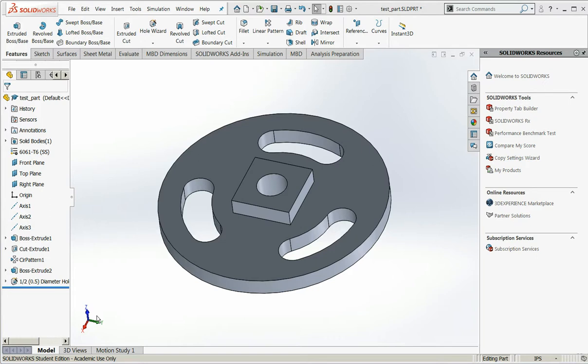If that's not the way you drew your model, what I would recommend is that you create an assembly, bring your part in as a component, and then export that part as a Step 203 file. Because I have mine properly aligned, we can go directly to the Step 203 exporting step.